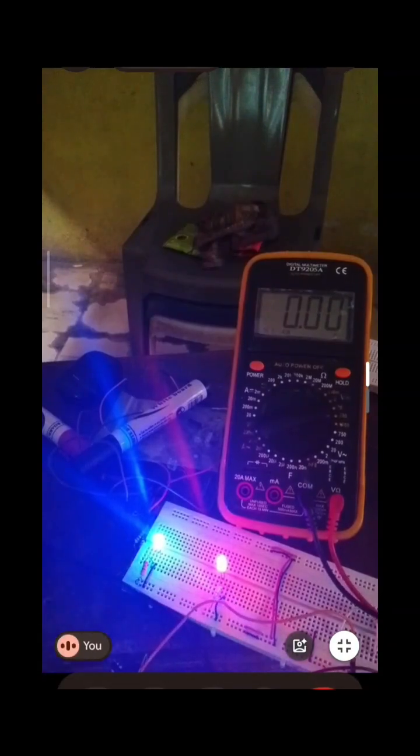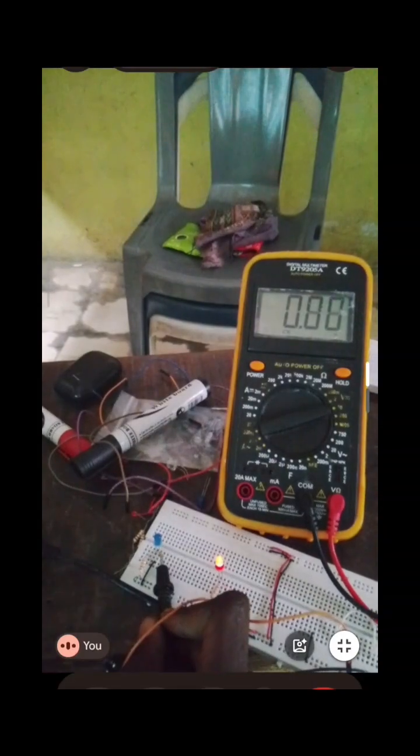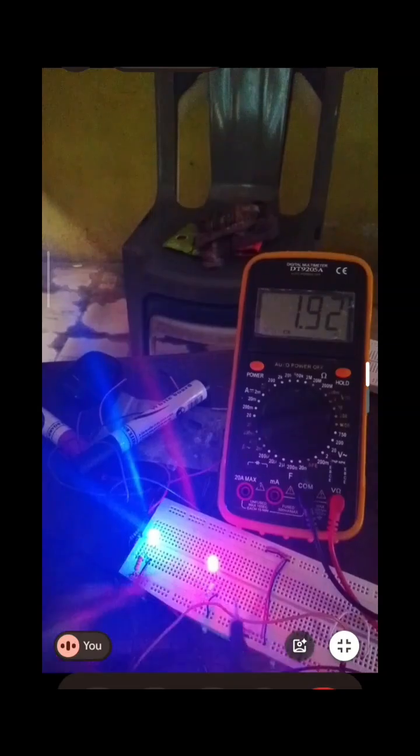Now let's see for this stubborn blue light. Can you see now? The blue light has turned on. The blue light is using 2.7 volts. Wow. To turn on. But the red light is using 1.92 to turn on. So now if we follow Kirchhoff voltage law, since this one is using 1.9,